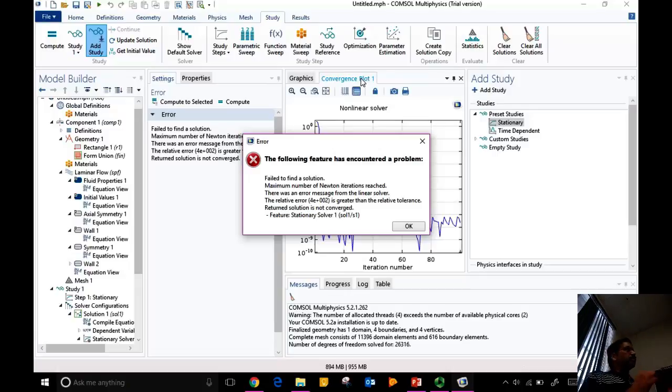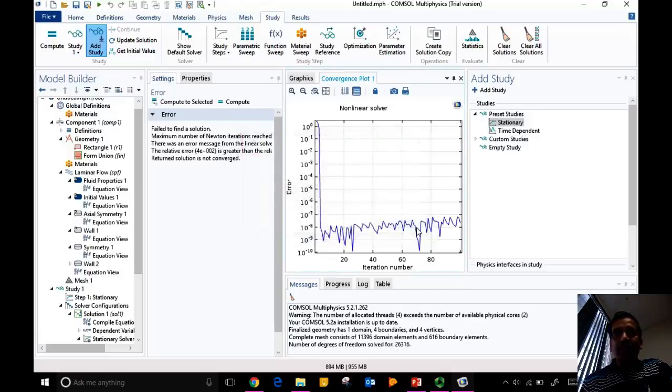So now we encounter the very first problem. It says no solution found. That means it is having a convergence problem. And what you see in the convergence is actually converged. The residual error has gone from order 1 (10 to the 0) to 10 to the minus 9. This is an acceptable solution. But the tolerance has been set so tight that it says it has not met the default tolerance.